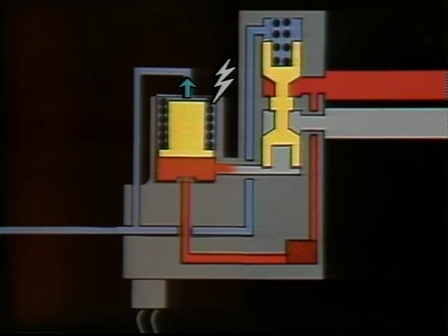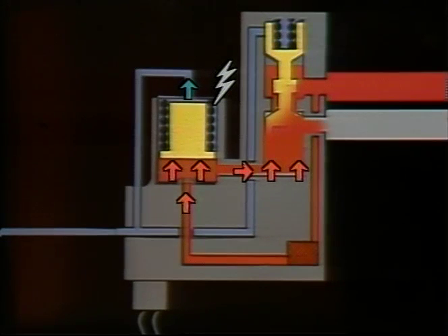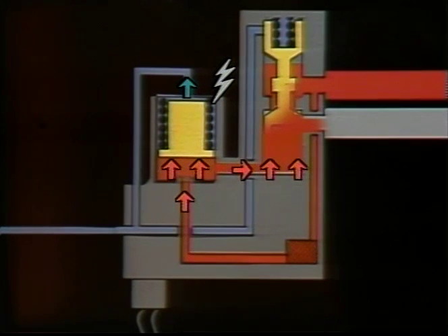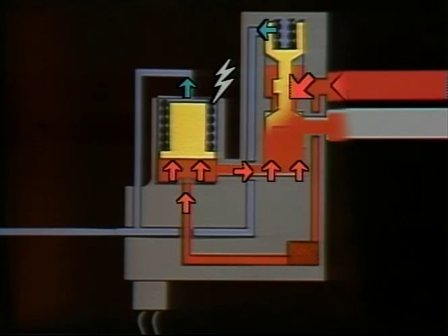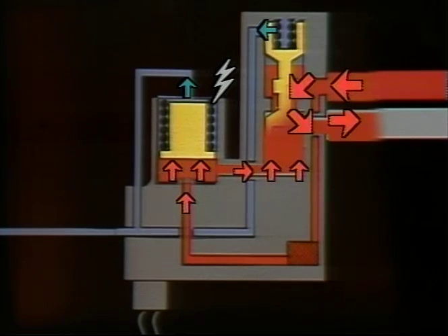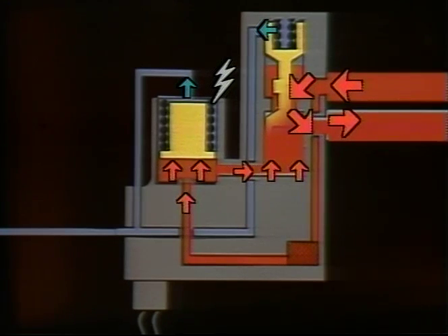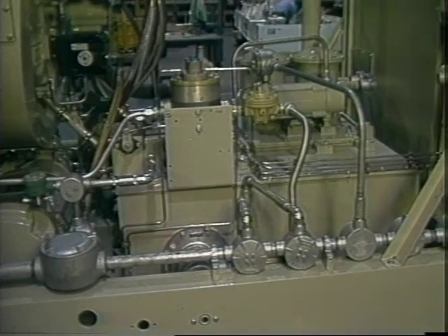Pilot pressure is now admitted to the open side of the spool valve, shuttling it to the open position. This causes gas at the closing side of the spool valve to vent. With the primary fuel valve fully open, supply gas can now flow through the open port of the valve to the secondary fuel shut-off valve.